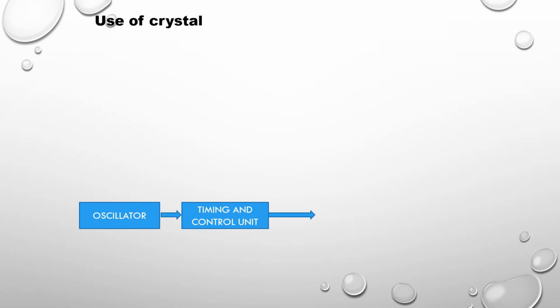So here the feedback is given with the help of an RC and LC network. That is why outside the crystal we have the RC and LC. So the RC and LC network will help the oscillator to give feedback. And this is my crystal. So the crystal, that is 6 megahertz, will be driving the internal circuitry. Here the internal circuit is nothing but your oscillator.